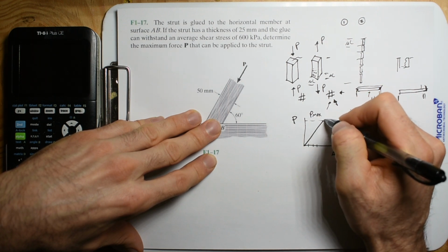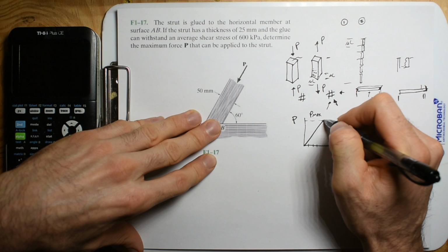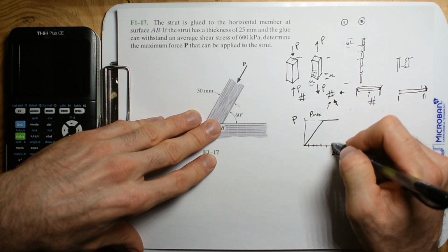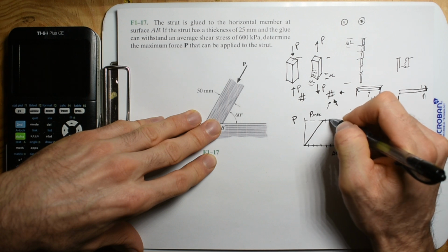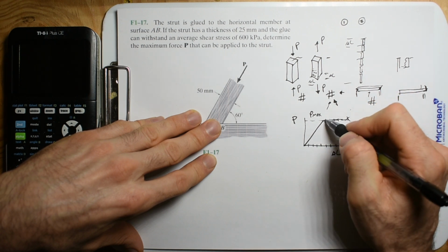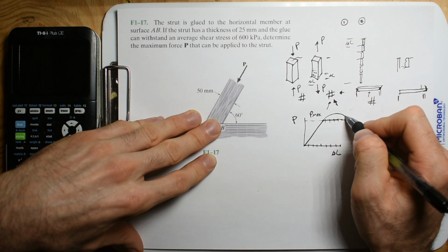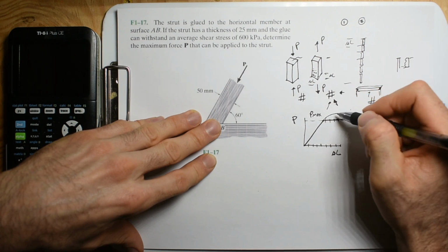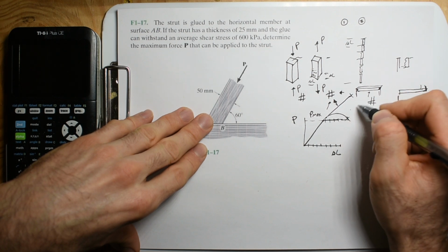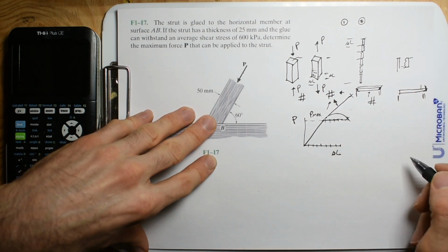If I put more than the max load, this line just flatlines, but I do see a change in length. The thing is just turning into taffy and then breaking. What really happens is it actually gets stronger, theoretically, because it necks down, and then kind of breaks.